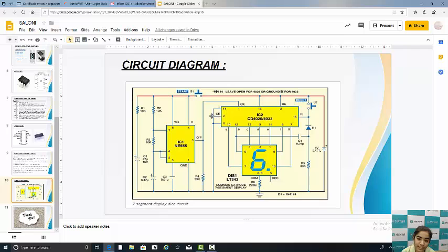The second one we connected with pin 8, and second and 8 are shorted. Then we connect to ground; the 14th pin is also connected with ground. The third pin we connect with the power supply, and 16 is also connected with the power supply.